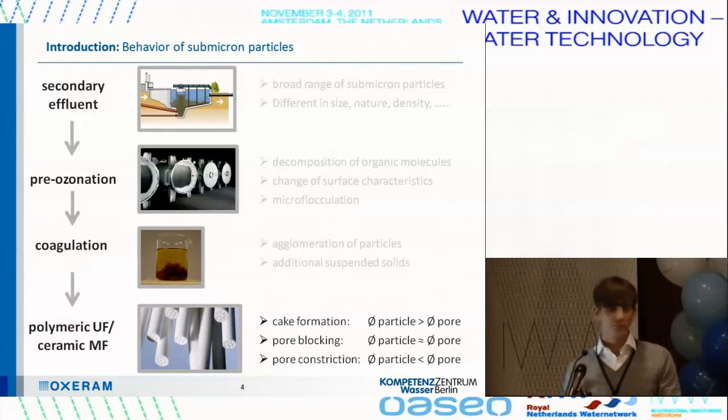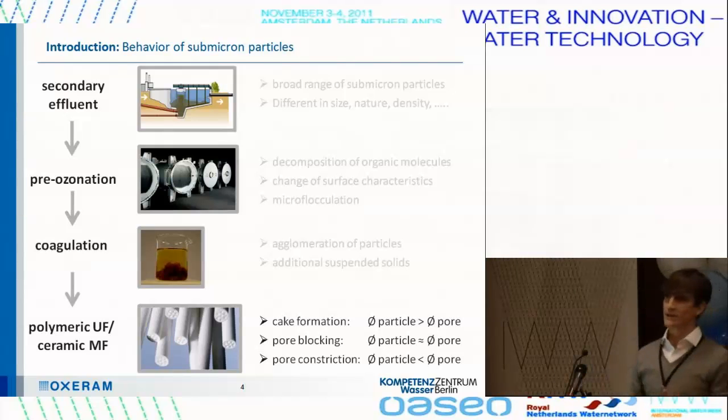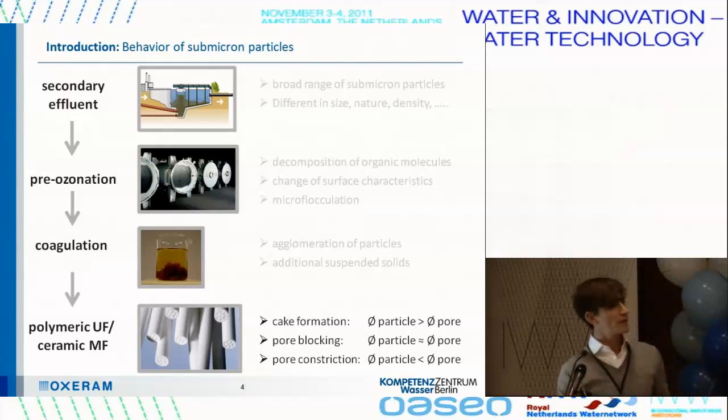And on the membrane, as you know, particles which are bigger than the pores form a cake. They can block the pores if they have the same size as the membrane pores, and they can cause a pore constriction of the membrane if they are smaller than the pores.